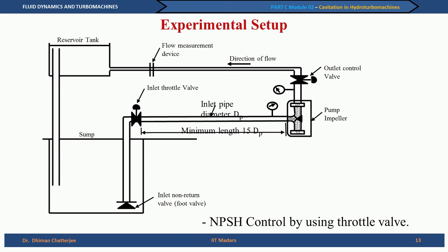The valve may cavitate first, and then what will happen? Downstream of the valve you will get lots of bubbles, just like the example I showed you with the venturimeter in the beginning. There will be bubbles downstream of the throat, and these bubbles will be fed into the pump. But that is not what we want to try. We want to try how a pump performs with normal water, not with water filled with bubbles.